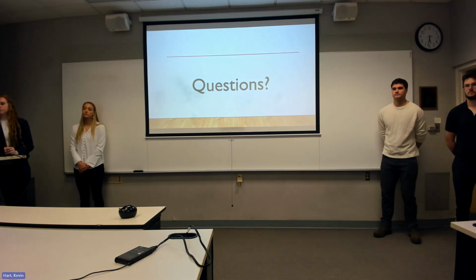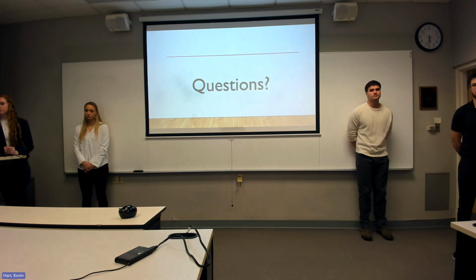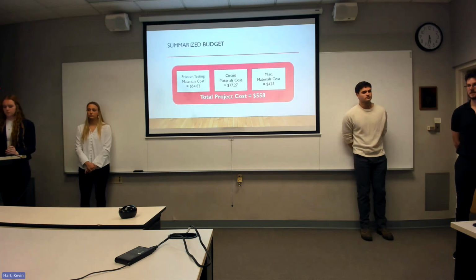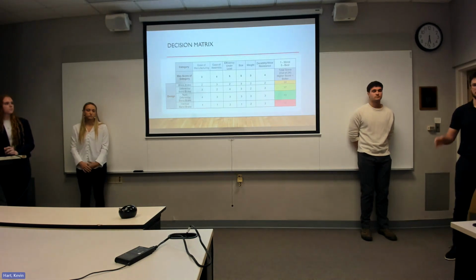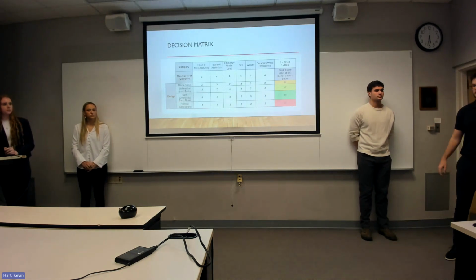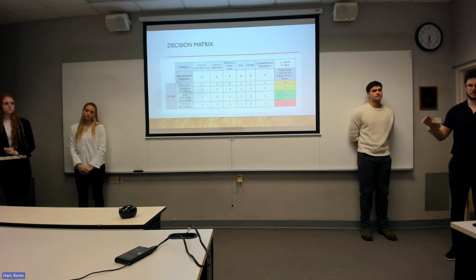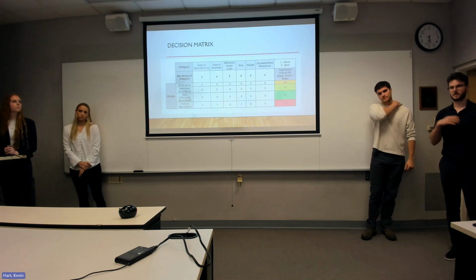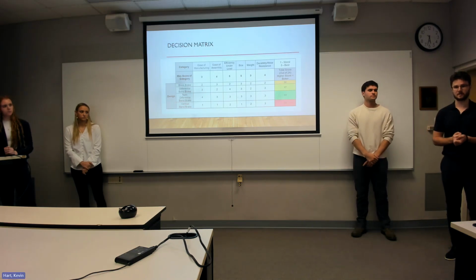And one question from the decision matrix, you put the weight based on the efficiency. How did you quantify the efficiency for different designs? By using the equations. We didn't really show it, but we had a whole spreadsheet set up where we would input the values based on the different lengths and where we'd be experimentally testing them. And we had the equations in the spreadsheet, and they were popping out coefficient of friction numbers theoretically. So we used those because we thought our test would be pretty representative and close to the theoretical calculations.